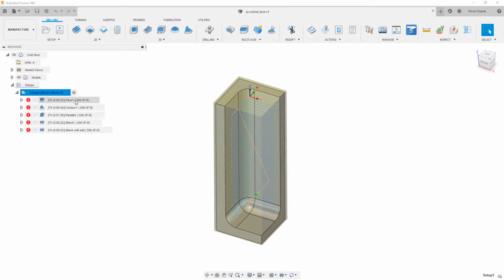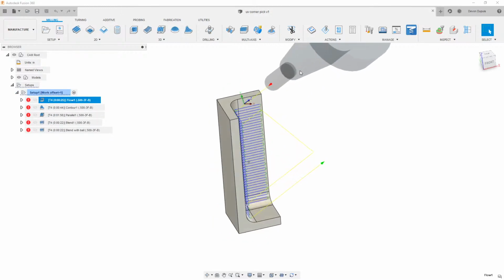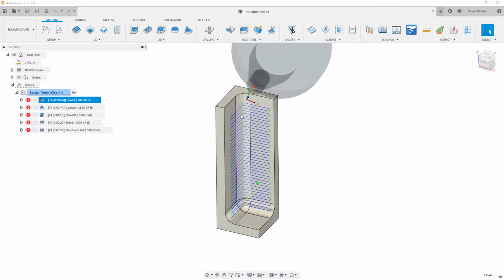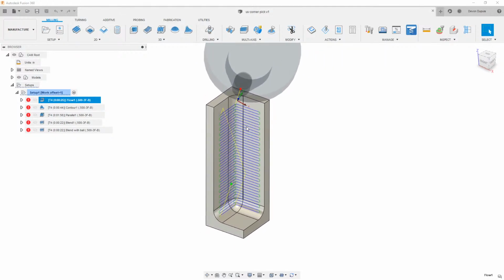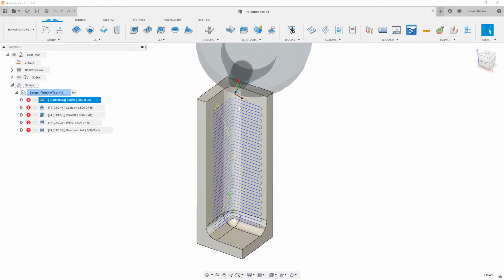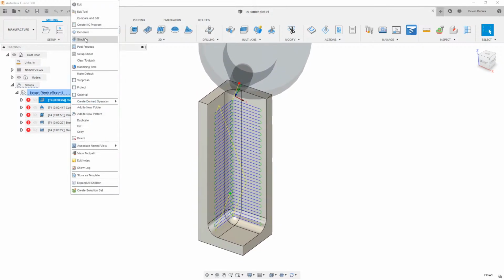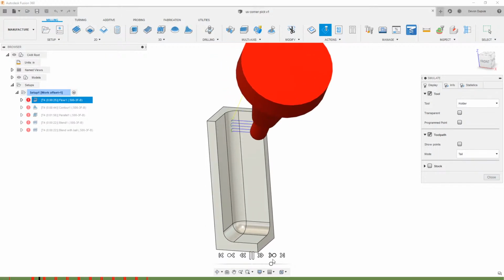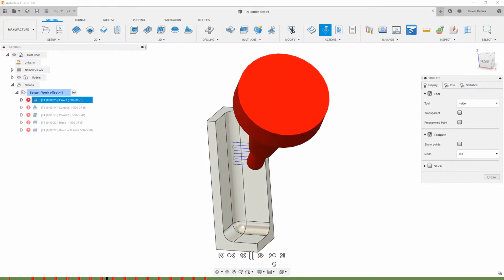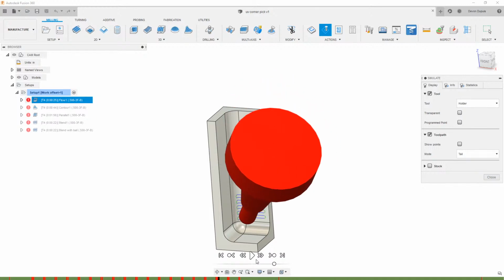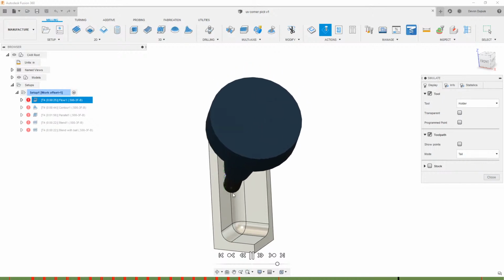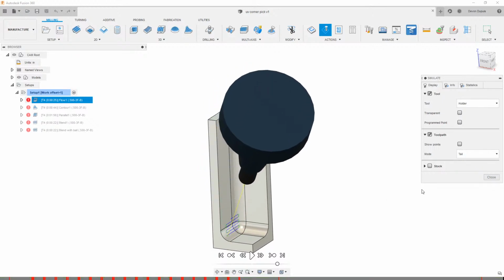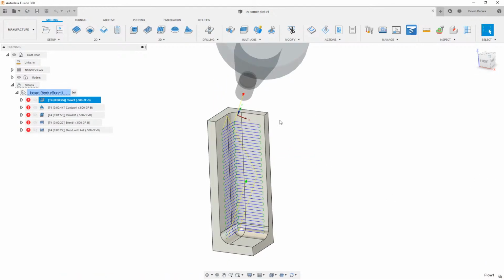Now, a lot of people might try to use a toolpath like Flow and just change the tool orientation. And initially, this looks good. The problem with this, though, is it's really not doing what we want. So if I right click on this and hit simulate, see, this is going to stripe back and forth. And really, the reason is, I drew this in Fusion, but the UV vectors are not connected. So once it does this side, it's going to flip and go to the other side. So it kind of does what we want, but really not in a very smooth motion.